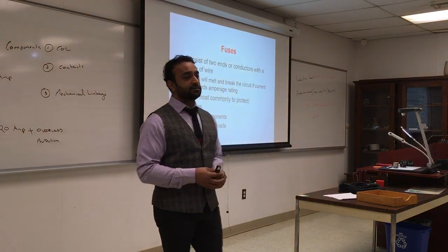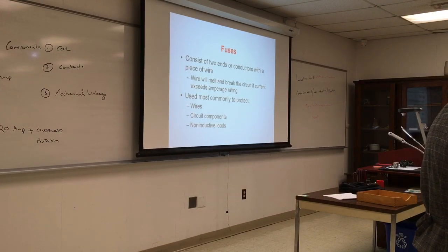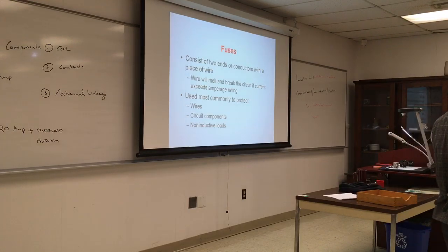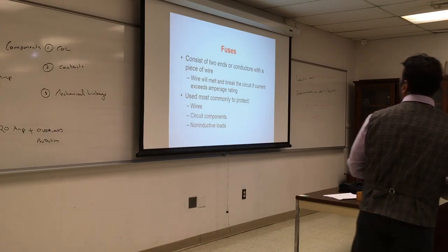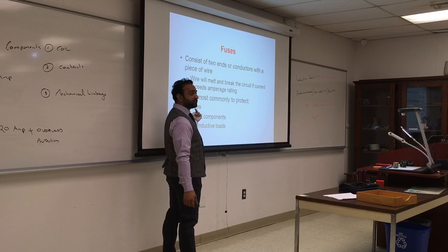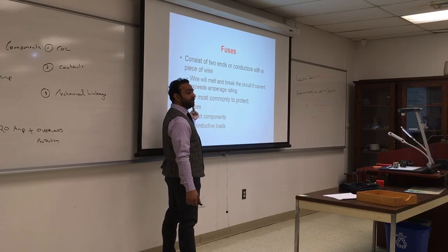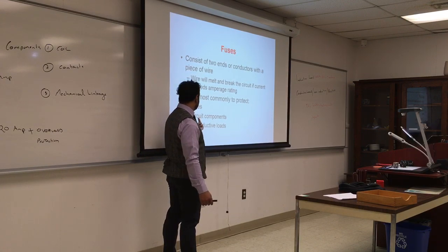That wire is specifically calibrated to melt at a certain temperature. And we said as we increase the amperage, the temperature will increase. And if you look at it, they're sometimes made of a mixture of nickel and lead. Lead has a very low melting temperature, so it just melts to protect your circuit. There are different wires. If the wire is rated at 15 amps, you put a 15 amp fuse on it, so it will melt before the wire melts.